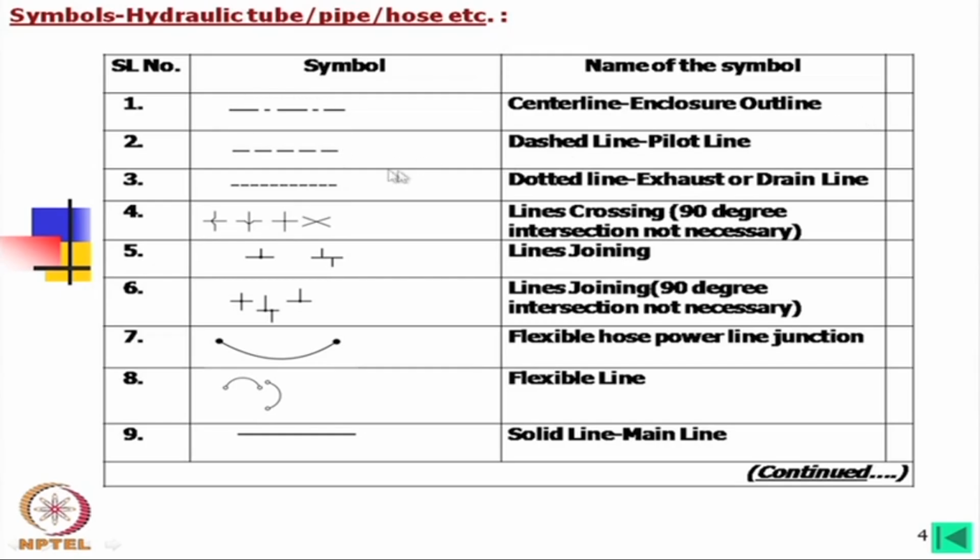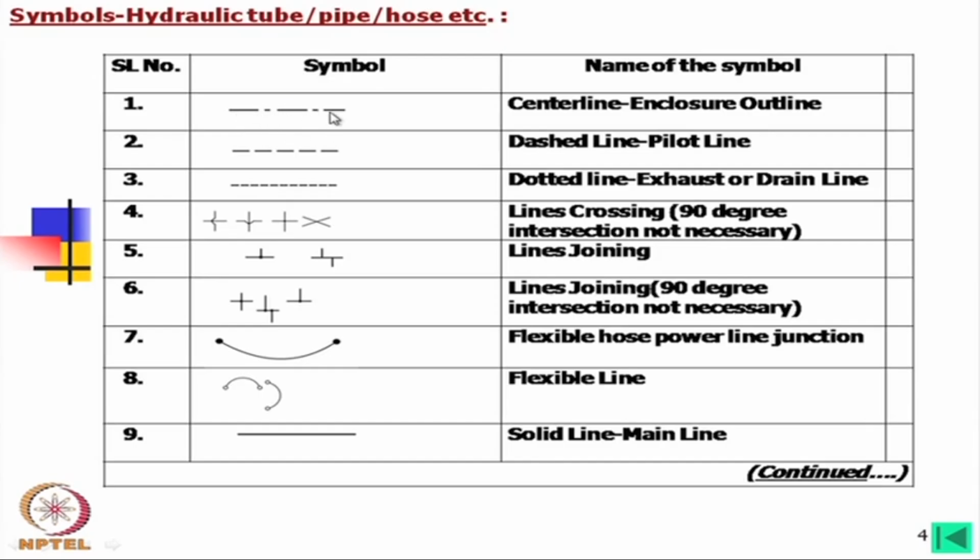That means sometimes we would say that there is a manifold. Actually, a manifold consists of a few valves together, and sometimes the symbol is like that. All the symbols for the components, like a pressure relief valve and direction valves, are drawn separately and then put in an envelope enclosed by this line.